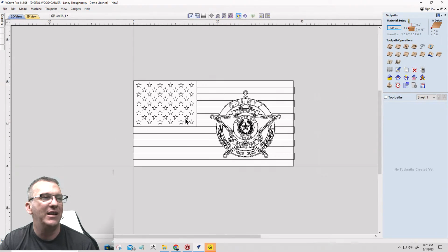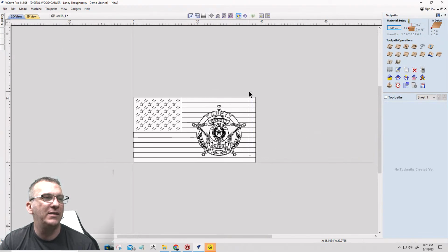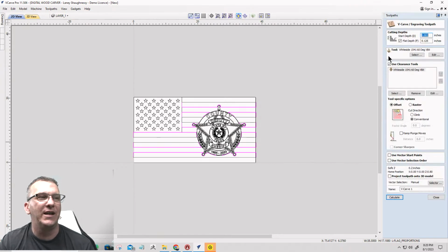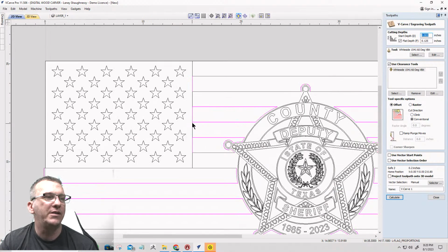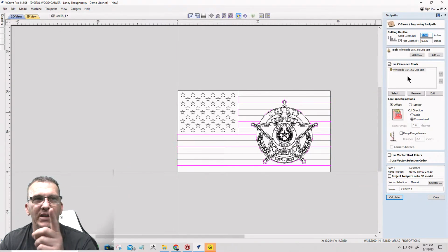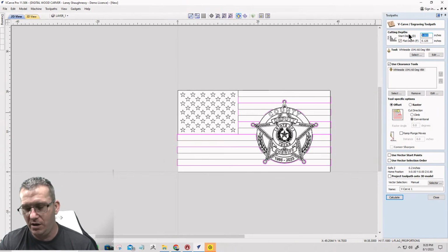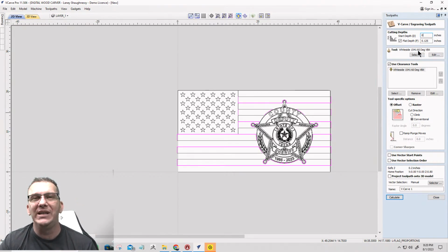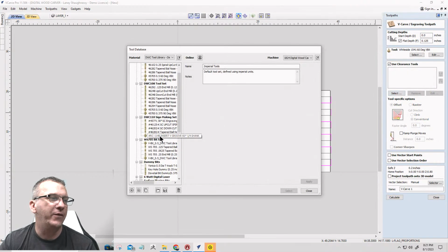It's not that complicated. Number 1, stripes. Select the stripes. We are not going to do a pocket cut. We're going to do a V-carve cut, so we get nice square corners. We don't get radius corners at all. We are going to start at 0, the start point. We're going to flatten out. I like an 1/8 of an inch depth. You can go however deep you want. I'm using a 60-degree V-bit, and I am going to use a 1/4 inch end mill for the clearance tool.